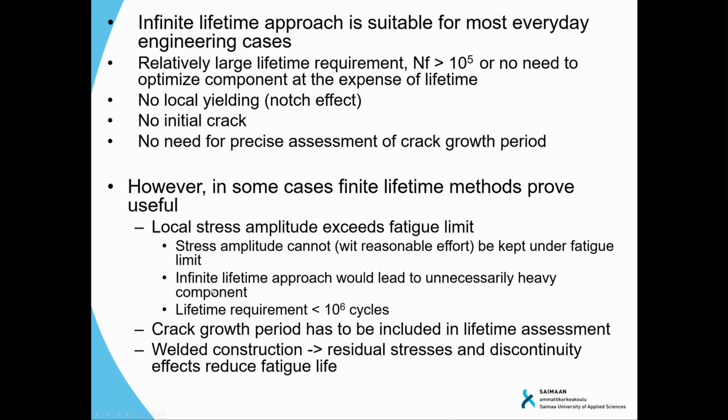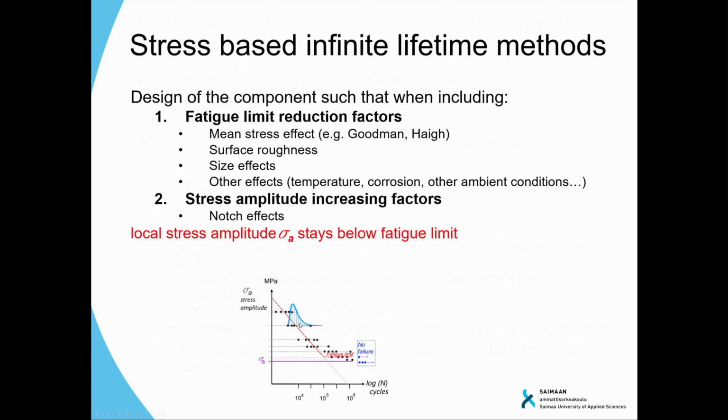And usually for these applications, the lifetime requirement is smaller, of course, because it will give us smaller lifetimes. But then it might be that we need to optimize the structure. We are not able to build the components so thick that we would keep the stresses below the fatigue limit. Therefore, we had to make them more slim. And then we are already in the region of the finite lifetime.